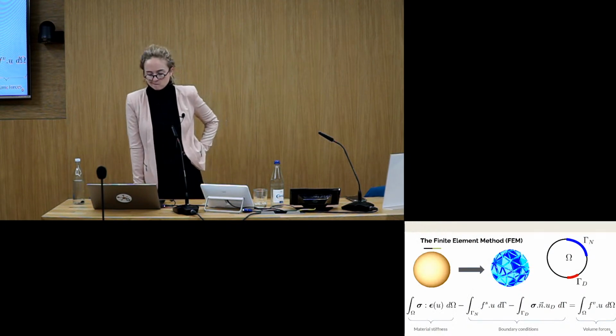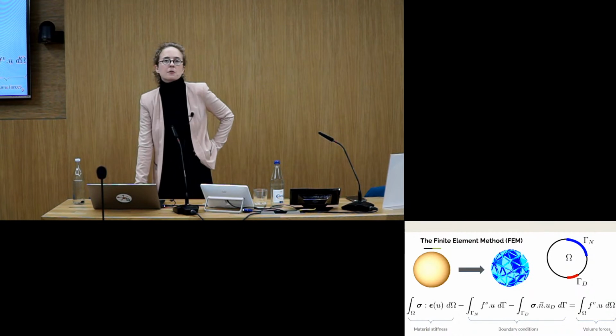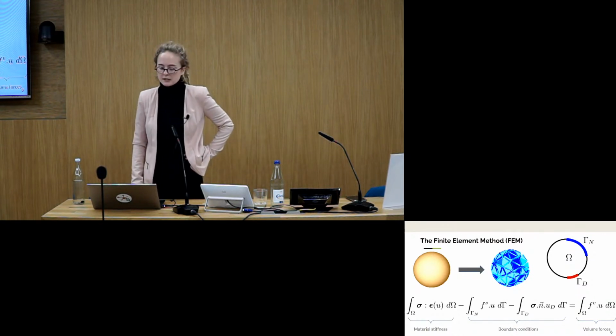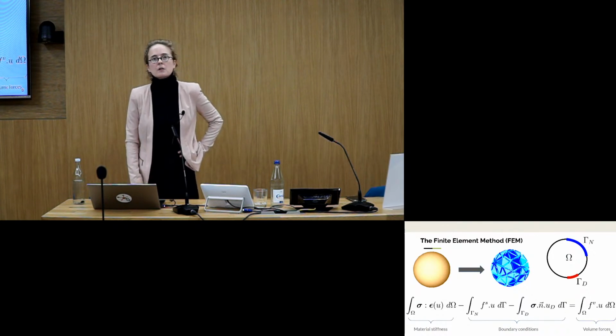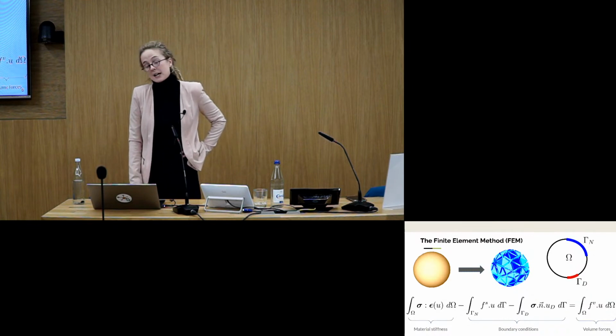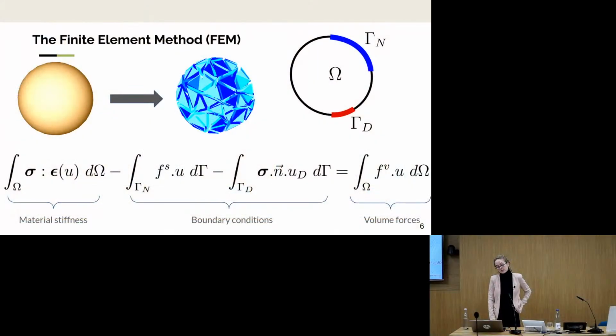Yeah, I did. So here it was only for the clarity of the equations, and I agree that this equation is limited to small strains. But indeed, I tried it with large strains, and not only with the hyperelastic Saint-Venant, we also tried training the network with the Neo-Hookean material, which is really a non-linear material, and it also works. So yeah, this was a simplification. Yeah, okay. That's clear.